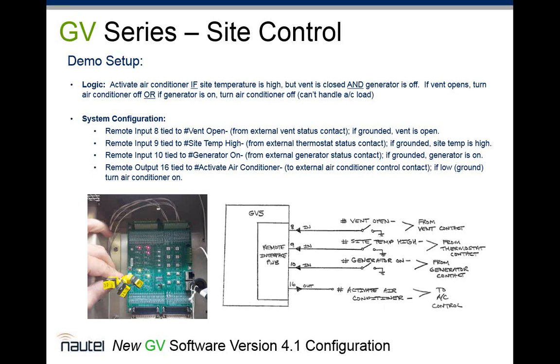So now let's qualify all this by saying, even though you could potentially start a generator, we don't have 600 amp contacts in the transmitter. So it may very well be that you're going to need to have an external contact or a relay or something like that, sort of intermediate control circuitry. That's right. What we provide is open drain in this case for the outputs. We provide open drain logical states, so they're either open or current sink to ground, and then the inputs are opto-isolated inputs where the user can, of course, leave the input open or some high state or current sink to ground to activate based on the logical setup within the system.